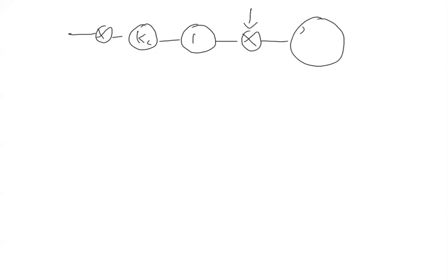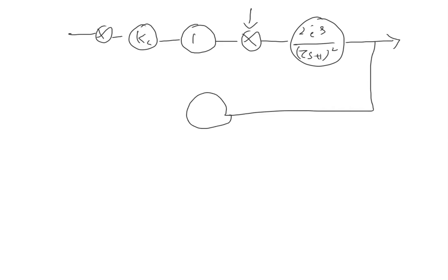So how do you calculate? The crossover frequency is already given as 0.6. First thing is you have to frame the control loop. It is a proportional controller. Here the valve and measurement transfer functions are given as unity. Sometimes they don't mention anything about valve and measurements; even if nothing is mentioned, you should take them as unity. Sometimes they will say they are instantaneous, meaning the transfer functions are also unity. What is meant by instantaneous? X is equal to Y, immediate.